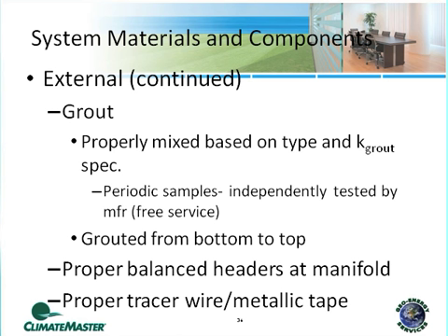All right, and then lastly here, before we get into some pictures, is the grout itself. We've talked about that earlier, using thermally enhanced grout versus your standard bentonite grout. Our standard practice, for me personally, is to always use thermally enhanced grout. The only time I've allowed bentonite grout is in winter conditions here in the mountains of Colorado, where it's a little bit harder for them to work with. For me, that's the only exception. Otherwise, it's our standard practice to always go thermally enhanced grout.